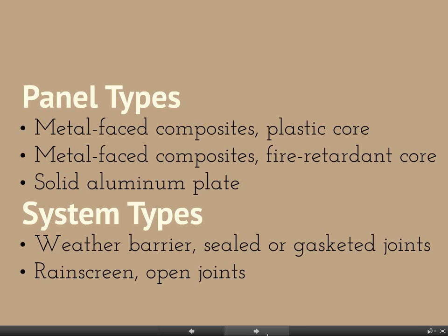Right. Vivian, you have a question from Rosa, and she asks, was there an issue with different sheen from the 2 coatings? Yes, that's the whole problem. It's not that the color doesn't match, it's that the color doesn't appear to match because of the different reflectivity from the way that the tiny little metallic particles are oriented. They tend to be oriented in one direction.